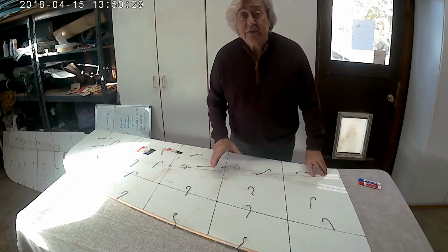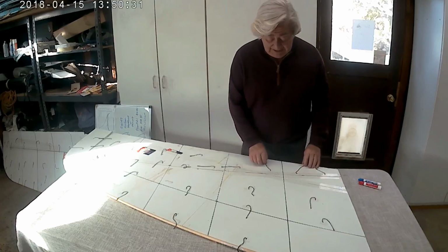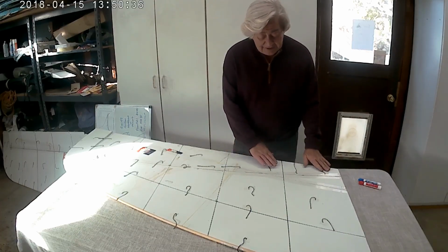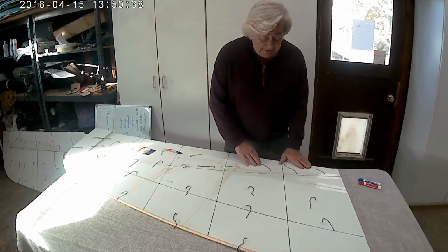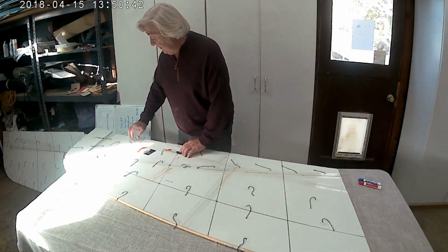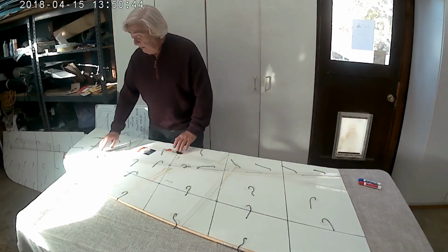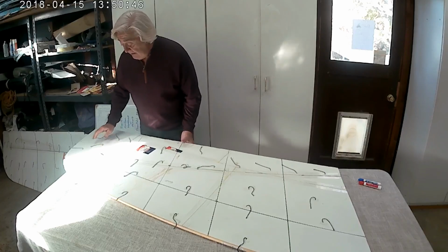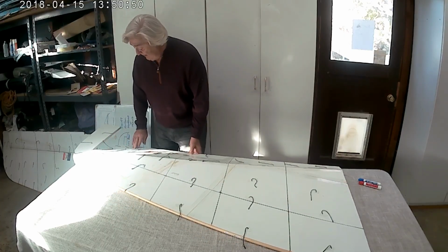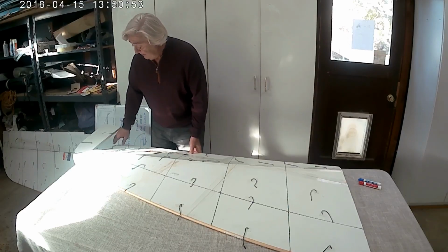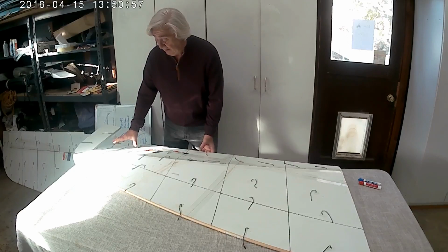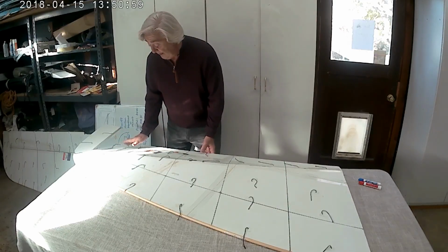The results were fascinating. Here's what happens. For deflections where separation starts to occur going down, we get the separated flow here, and these guys go out like this, and we still see a little bit of that out here on these tufts, but not these guys up here. So the elevon's down like this, and these guys are still going straight, and these guys are starting to go out towards the tip. Well, that's an improvement. At least we have a portion of the elevon that the flow is staying attached, not separating.